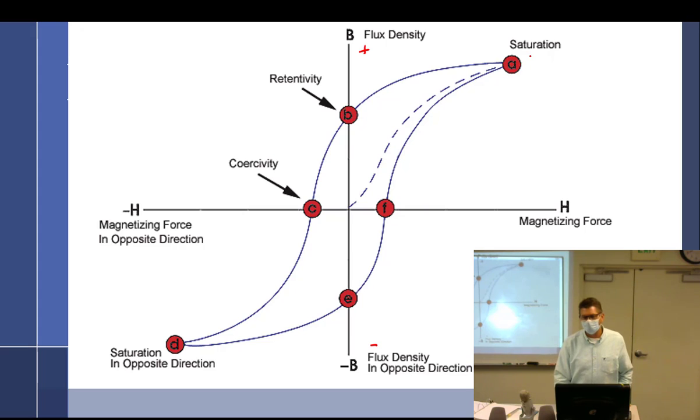It's just to the point where that part has become 100% magnetized. And that has to do with the material it's made out of. Exactly. Okay. So now this is that saturation point. That's with the power on, the button on. It can't get any more magnetism. But as soon as I release the button and I'm no longer magnetizing it, it's going to roll down to retentivity. That's what's left. So that's the difference.